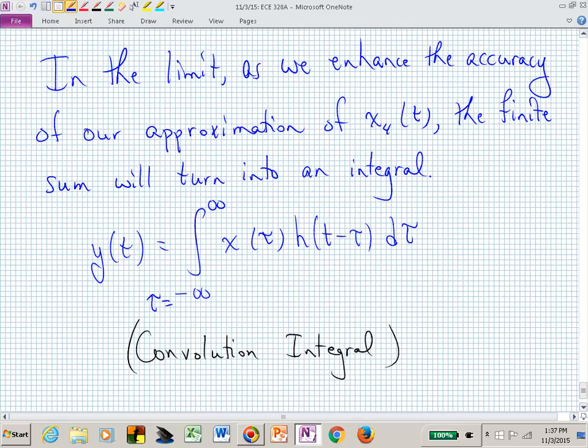So we're flipping h, and we're sliding it through time, 6, 7, 8. That's where this flip and slide comes from. And we also need to figure out where the limits of our integration need to go, because our waveform might change shapes, and that's this limits and intervals piece of the process of doing convolution.